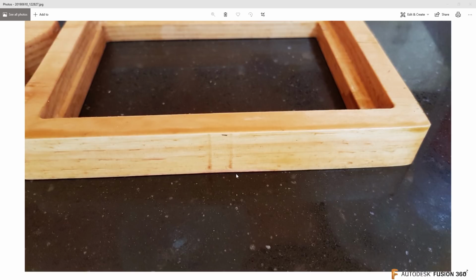So I'm looking at this, and you guys may also be sticking your nose on the screen here. I'm assuming, Christopher, we're talking about these two vertical lines here. It could be gouges, I don't know, but it also somewhat looks like it's the wood. If these are the ones you're talking about, then there's something up with your tool possibly hanging out too far, and your feeds and speeds are not great, and it's whittling around in there maybe. I'm not sure. But if it is these two here, there could be a couple of different things.